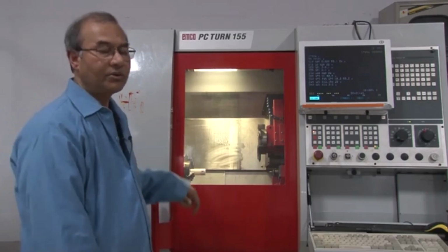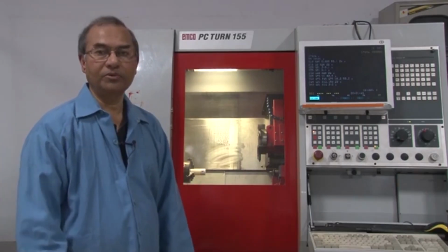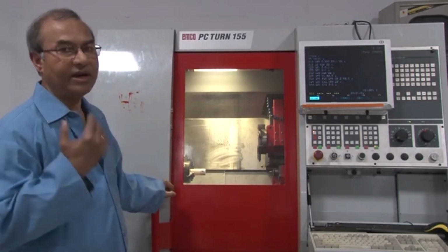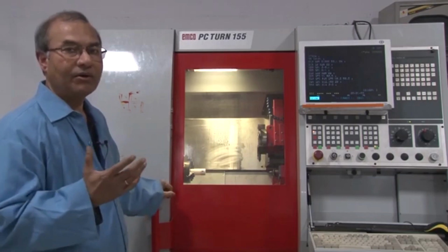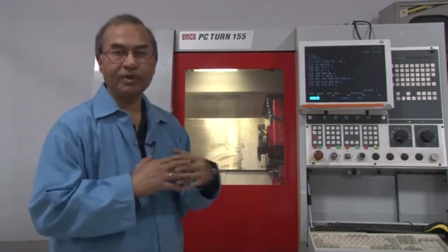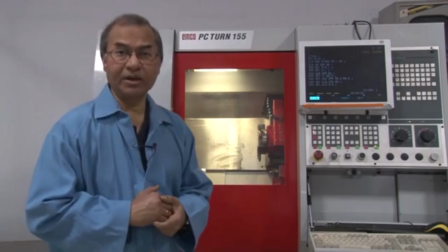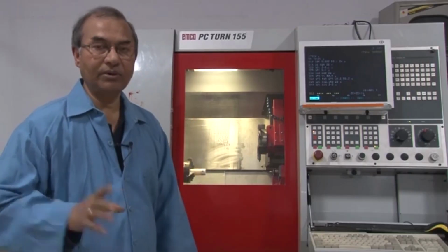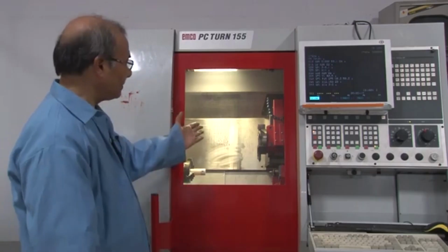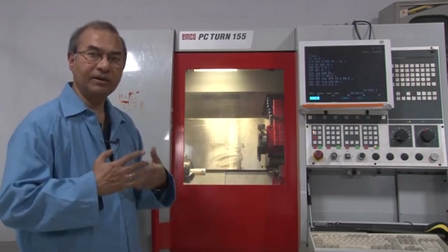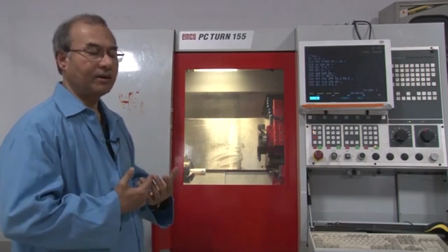Now that program also, I would like to remind you, we have shown you how those programs are to be tested before we put them in the machine, because if there is any fault or contradiction in the program, there may be an accident, because there may be some clash between the tool post and the spindle, and they are rotating at a high speed. So therefore we always test it, simulate it, and when we find that the program is flawless, then it has to be put into the machine, and the machine will automatically make that part.